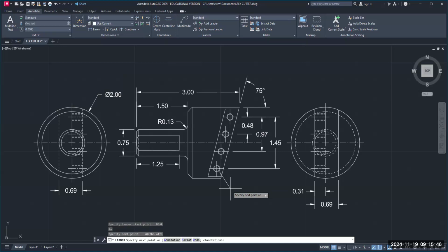Click. Now watch, you got the little tail here. Look, that's going crazy. Hit F8 again. And we're going to click right there and then enter. That wants to enter the text. And we're going to type in 10 dash, the minus sign, right? 32. 10 is the diameter, 32 threads per inch, unified national fine, UNF